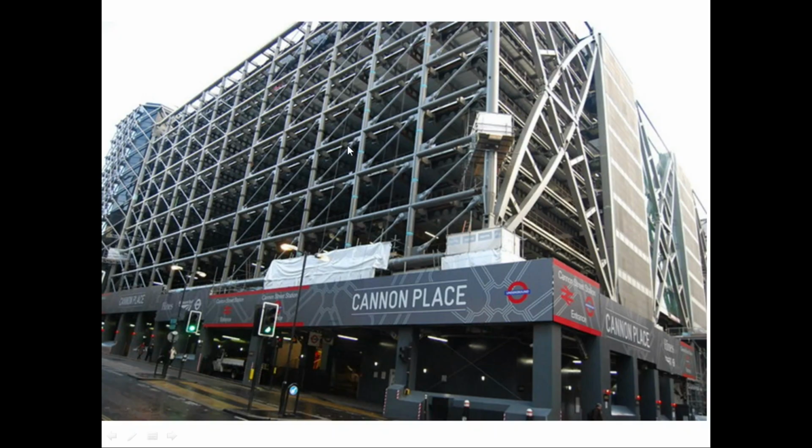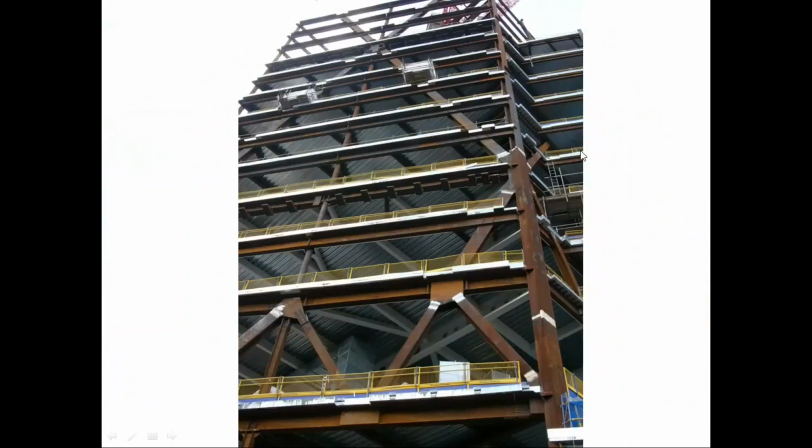This solution here, as you can see, has lots of struts in pure tension, steel rods, in both directions, that way and that way, bracing that facade for any lateral loads. And on this side, some rather large and dramatic triangulations, which again, not one huge piece, but broken down into a couple of opposing trusses, solving the same problem.